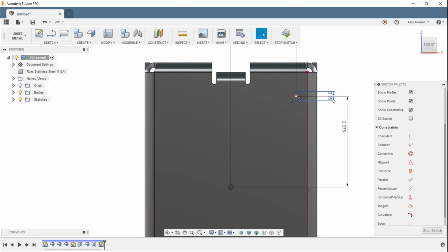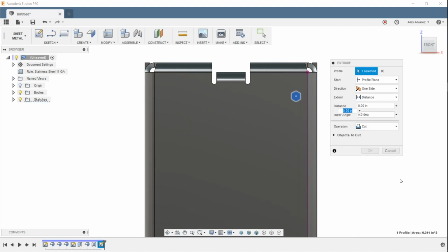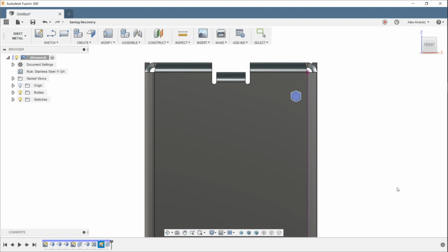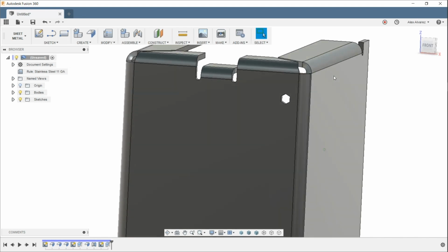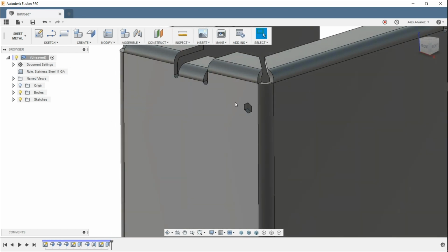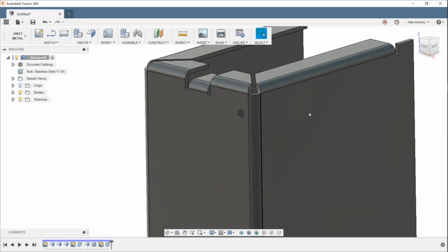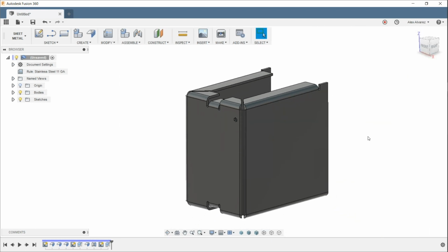All right, go ahead and extrude cut that, and say minus D3. Right. So again, sticking with that thickness parameter that we had. Right. So minus D3, and it gives us the cutout. And again, if this ever changes thickness, that cutout is also gonna change thickness along with it, right? So again, let's go ahead and pattern that.